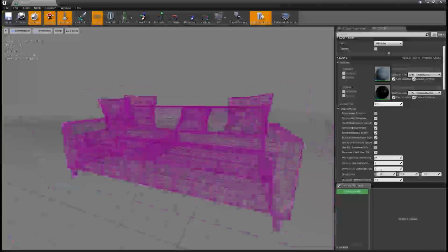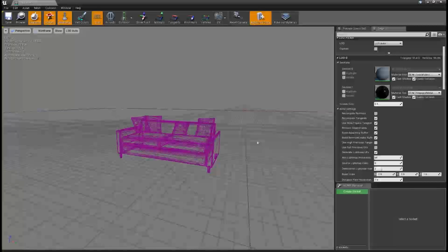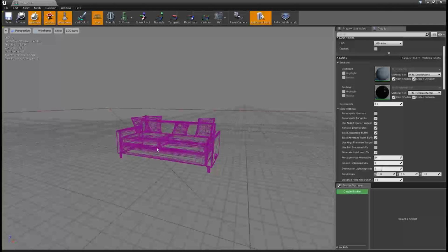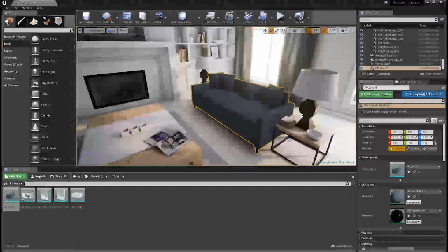or less. So we can see now it jumps from LOD 0 to LOD 1 when it's about 50% of the screen. Obviously, we'd want to change all of the other LODs as well to match those settings. Although the scene we're working with is really too small to benefit from LODs, LODs provide a huge benefit to performance in a larger scene with a greater view distance. Using them could very well make the difference between a walkthrough that runs poorly and one that doesn't.